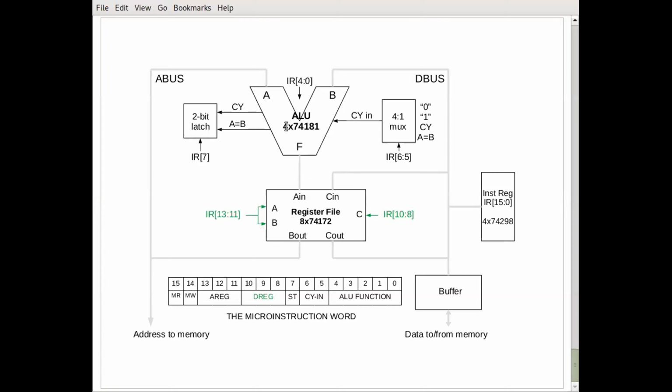Yeah, that's the problem. That's that 17th bit that I wanted to avoid using. No, you use the 2 bits. So instead of memory read and memory write, bit 15 is memory enable, and bit 14 is, if it's 1, it's reading, if it's 0, it's writing, or vice versa. So you've implemented your own halt and catch fire function. So you can have your tri-state then. You can either read or write, or you can have no memory access at all.